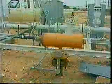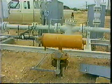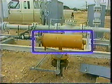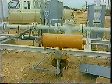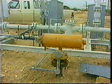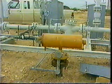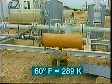The density of an NGL stream is determined by use of a gravitometer, or more typically, a densitometer. The densitometer measures weight per unit of volume as compared to water weighed in a vacuum. If a gravitometer is used, it records a specific gravity of the liquid stream, and then the reading is converted to density by multiplying by the weight mass of water per unit of volume in a vacuum at 60 degrees Fahrenheit.